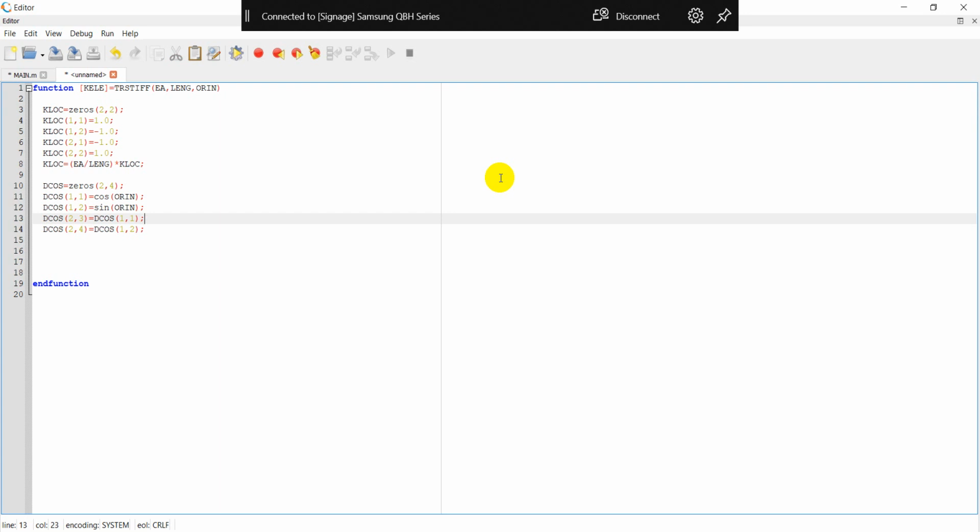The thing is that doing the finite element analysis or direct stiffness analysis, that's a lot of loops. You have thousands of elements in there. That means if you have waste in an operation like this, it will be repeated 1,000 times. If you conduct nonlinear time history analysis, your stiffness matrix might be updated due to the effects from the nonlinearity. So softening is coming in, the structure is nonlinear.